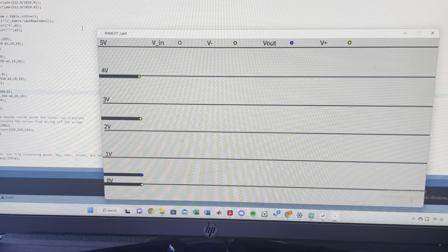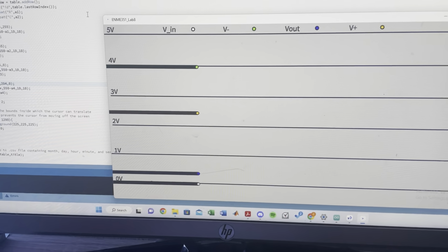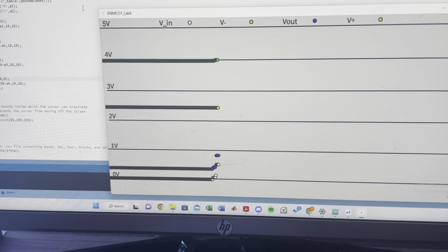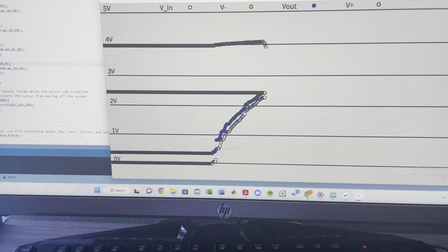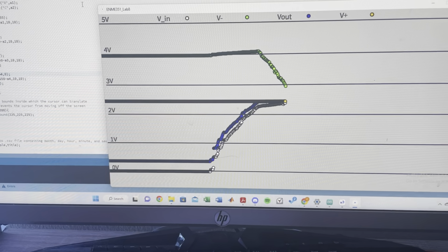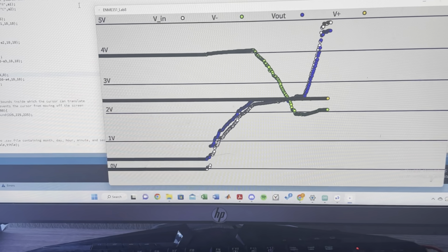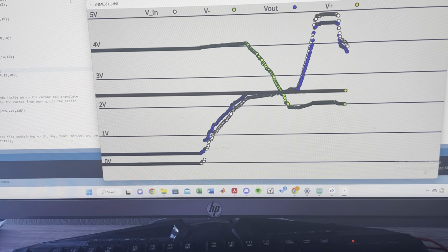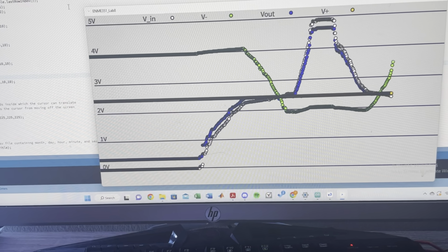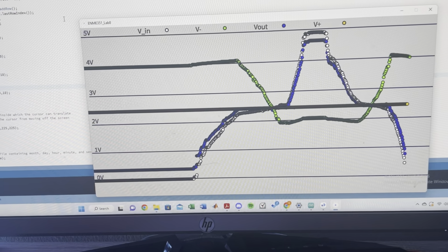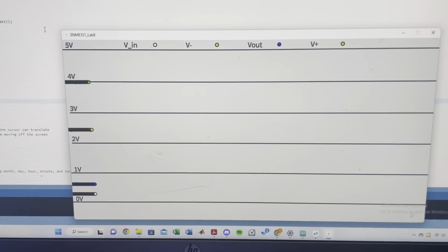At 0, the offset voltage shows up as 2.5, and as Vin is increased up to and past that offset voltage, then Vout inverts back down to 2 volts. And it does the same as you cross that boundary again, turning back the potentiometer. So you can see it runs between 2 states and is inverted after it passes that offset voltage.